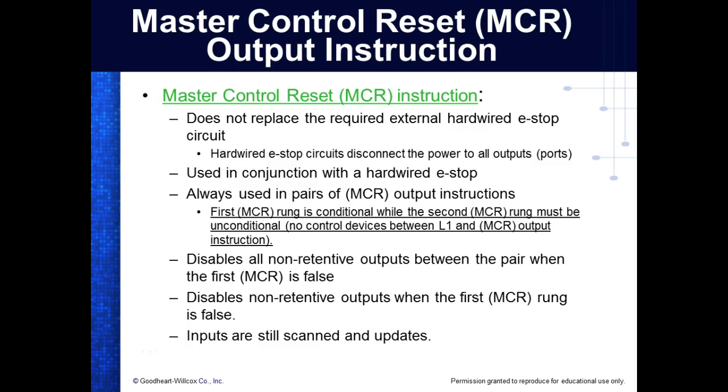By the way, if we're going to do that, we're not going to do that with a PLC. We're going to do that with a relay called a latching relay. I think I showed you that, right? So if we want something to stay energized when I kill the power to my PLC or something happens to my PLC, then we're going to latch that sucker outside of the PLC. Does that make sense?